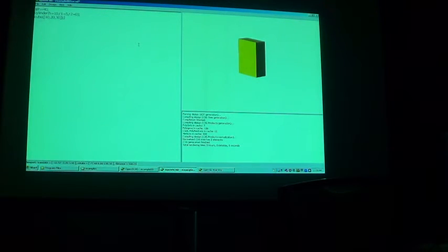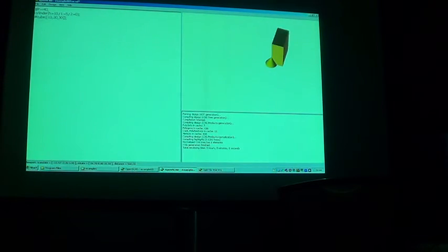Arbitrary shapes. See, it's inside of there. And if I want to see, well, where exactly is my cylinder, or what exactly am I covering? It's just a neat little pound sign. It works kind of like a comment if you're familiar with software design. And so it'll actually highlight the object that you have the pound sign in front of. So you can see the cones there. They look like they're joined.